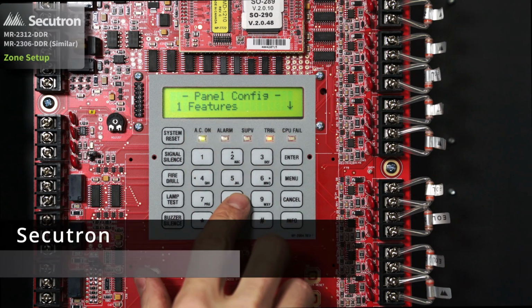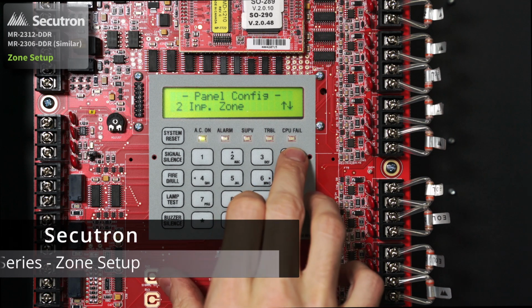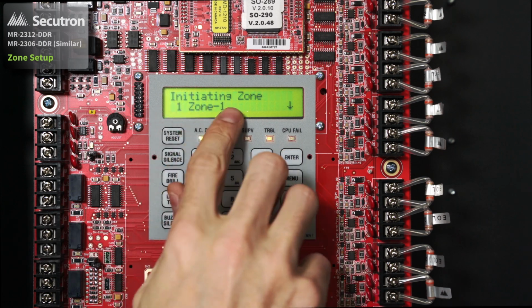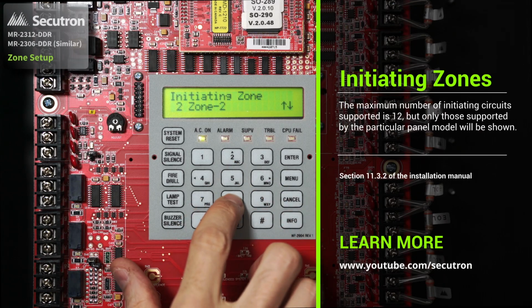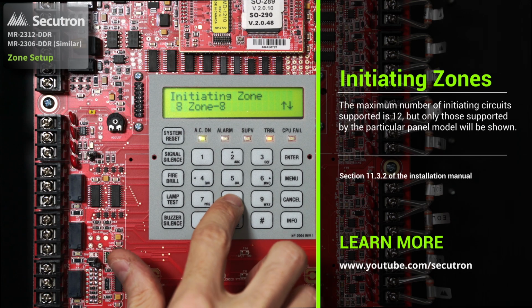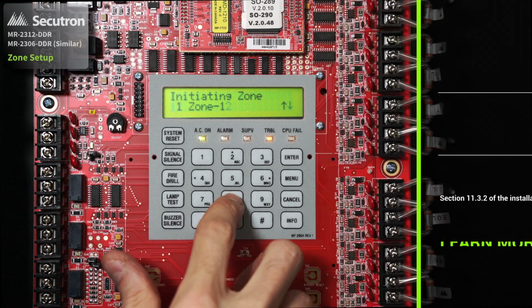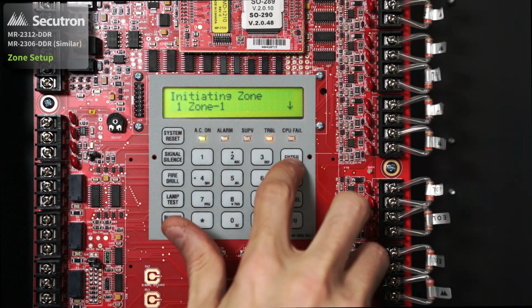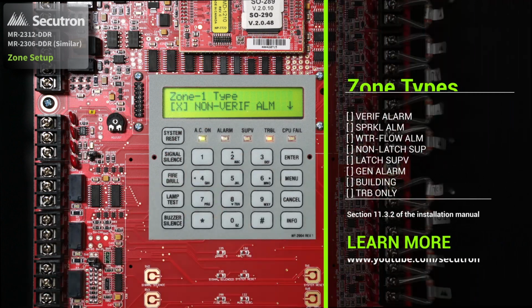In panel config, after features, we have input zones. If we select input zones, we can see a list of our initiating zones. On here we can see a list of 1 through 12 as we are using the MR-2312, so it allows us for 12 zones. Now with one of the zones, if we select, we can hit enter, and from here we can select what type of zone this zone will be.